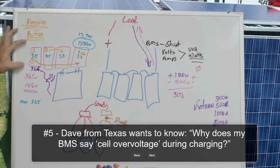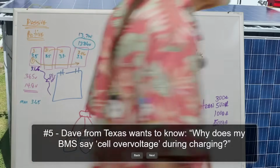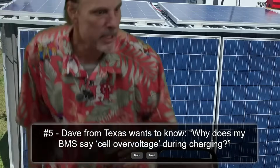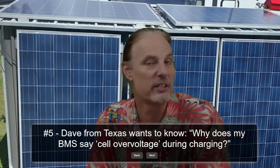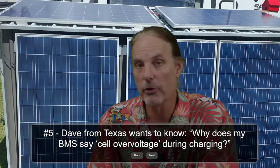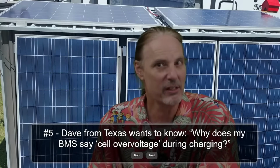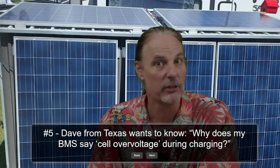Now, this is why he's seeing, and I think it was Dave from Texas, wants to know, why does my BMS say over voltage during charging? And that's why he's seeing the over voltage during charging. One cell has gotten to that limit where it is no longer safe for that battery pack to charge. And since that cell could be damaged if it allows it to continue, it's going to shut that off and it's going to stop it.